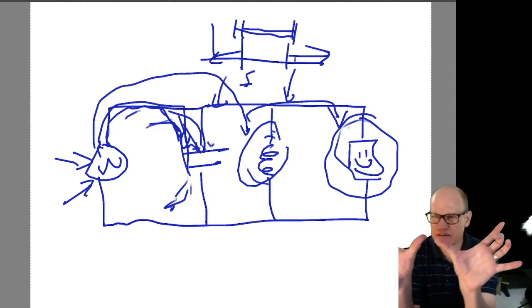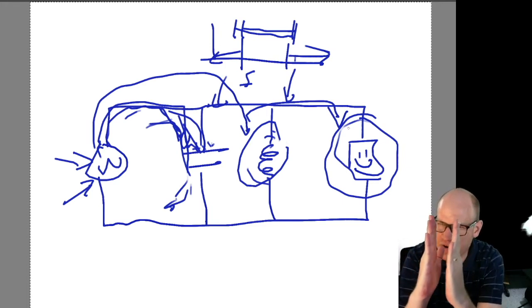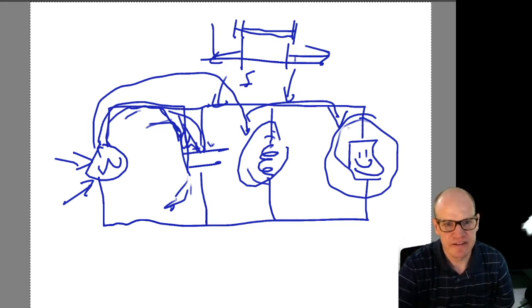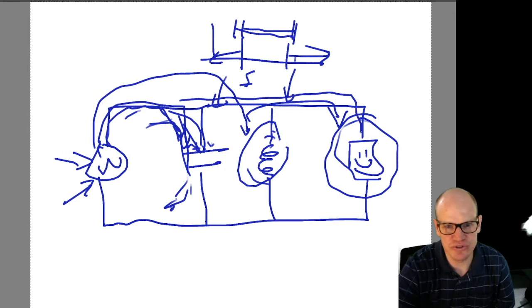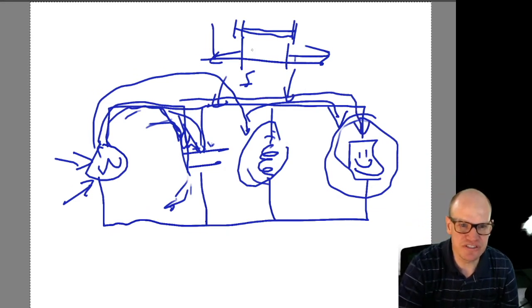So you can choose your capacitance and your inductance so that you can narrow down the band that's accepted, the band that actually goes through your, say this is an amplifier or something like that. So you can choose these things so that you get a very narrow band like this, and then you're only sensitive to some source that has a small bandwidth.